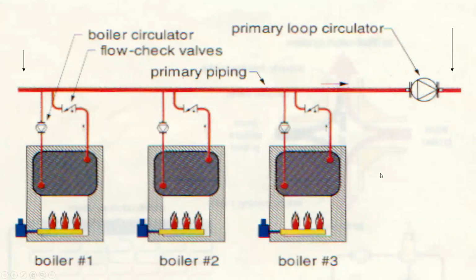Here's 3 100,000 BTU boilers that replaced one big 300,000 BTU boiler in an apartment building. And the guy pipes like this. He goes, I've heard about this. Isolate the boilers, do primary, secondary. I'm going to do it. I'm going to get 3 smaller 100,000 BTU boilers, each with its own pump. I'm going to do primary, secondary, and I'm going to keep my big distribution pump that handles the whole load out to the apartment. And this is the one downside. And some boiler manufacturers still promote this. They show this in their installation manual, the design manuals.